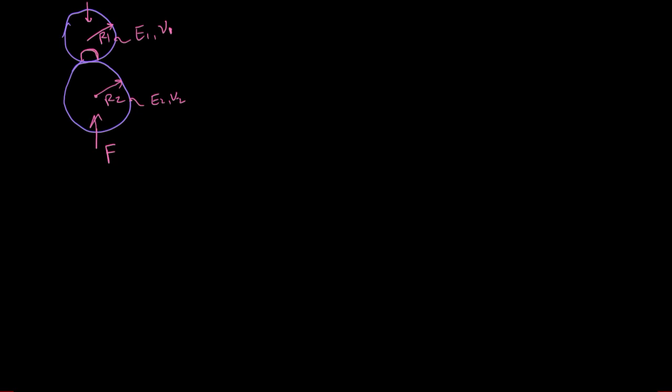And it turns out that if you take a look at the actual stress distribution or the pressure distribution between surfaces, you have a profile that looks sort of like this on the material, and in the center you have a max pressure on that surface, and that max we call P naught. Okay, so P naught is the max pressure, and this max pressure is also the stress in the z direction. And so these are the important parameters, the two radii for the two balls.